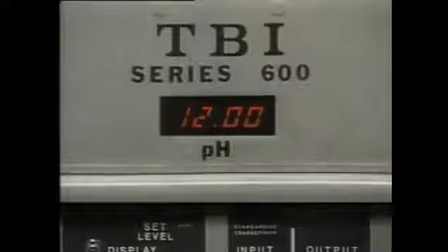A low pH means the water is acidic. A high pH means the water is alkaline. A relatively low pH tends to increase the likelihood of corrosion, while a relatively high pH tends to increase the likelihood of scale formation. If the water's pH is high, acids such as sulfuric acid, which have a low pH, can be added to lower the water's pH. On the other hand, if the pH is too low, an alkali is added to raise the water's pH.